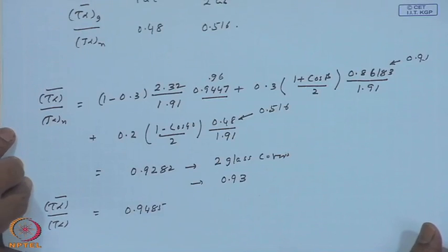So, as I was emphasizing, this 1 plus b 0 into 1 by cos theta minus 1, the incidence angle modifier coefficient relation for tau alpha by tau alpha n in general, depending upon the theta that you use for the direct radiation or the diffuse radiation or the ground reflected radiation, will give you the appropriate tau alpha by tau alpha normal. So, we got this.